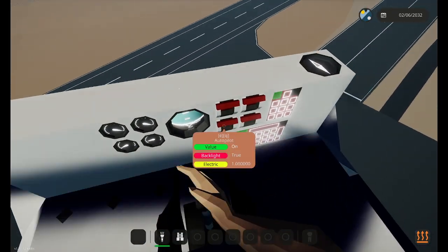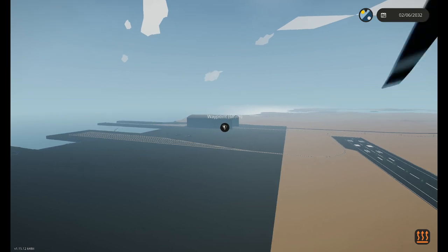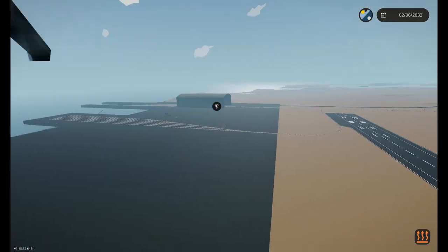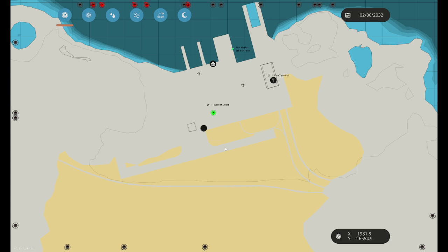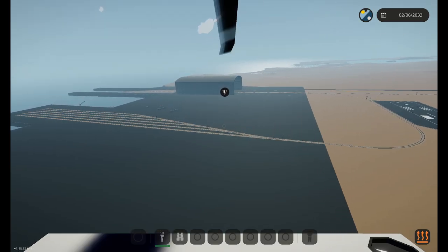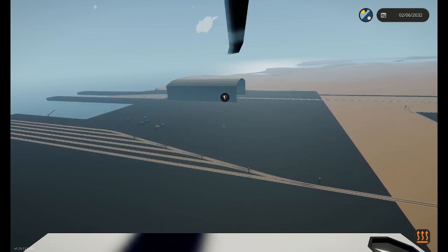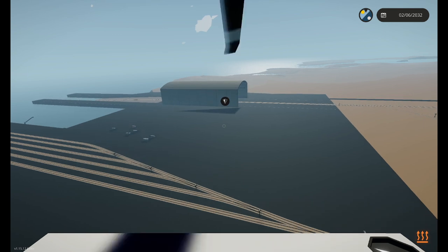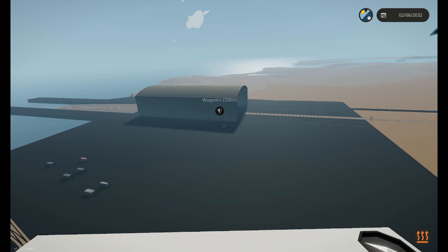Alright, turn it on, and you'll see immediately we start flying towards the waypoint there. It's pretty rock solid. I've tested it in every conceivable direction. It's important to do that if you're building an autopilot, because if you don't, it might do just fine going east or west, but it might invert north or south, or the other way around. So, it's just part of the testing process.